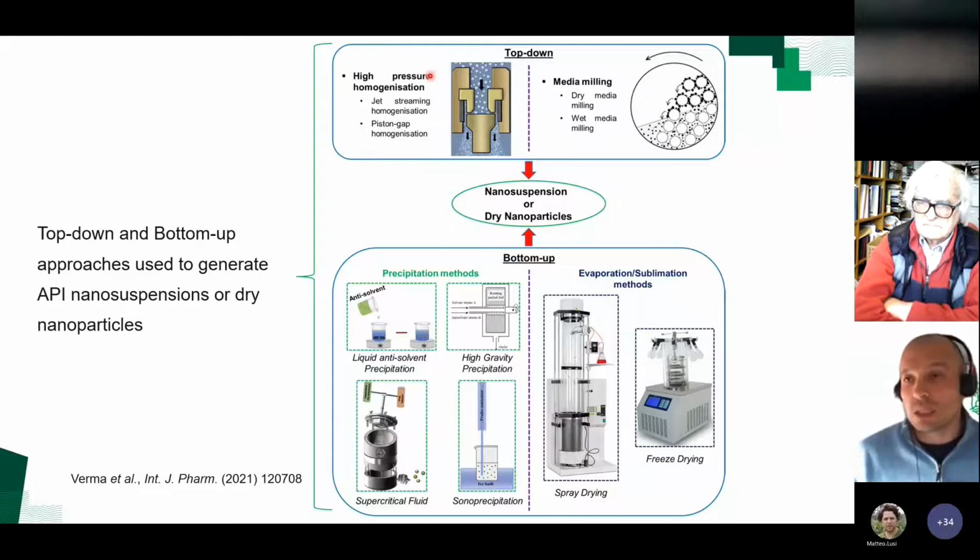So that's suspending pharmaceutical drugs in a non-solvent, or you can also use dry milling, which is using different methods. Here it's just a representation of bead milling, where you're using stainless steel beads to grind your particles in the rotor. So your particles, which are pharmaceutical drug, they are being broken down by these stainless steel beads.